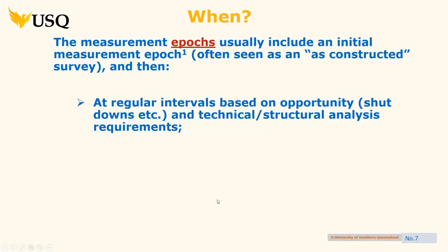Regular intervals: do you do regular intervals or irregular intervals? You'll see later on, for example, we're in a heavy drought period at the moment. Now, do we actually measure the big dams now, because they're unloaded, and there's not a big water pressure on them? And then measure them when the dam's 80% full to see what the deformation is. Or do we go along and say, here's the contract, you have to come every 6 months, every year and do these sets of measurements? Well, you'll see later, I'll show you how you might end up with the wrong time period to measure.